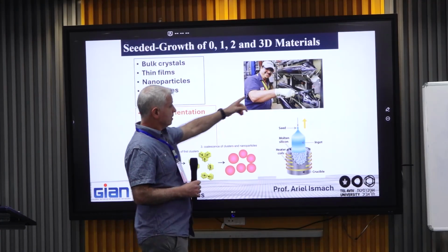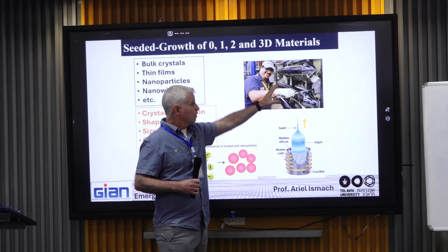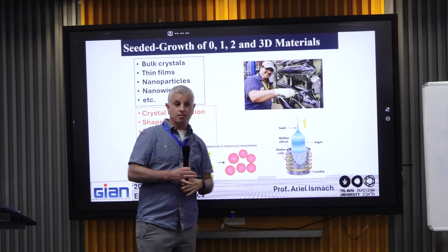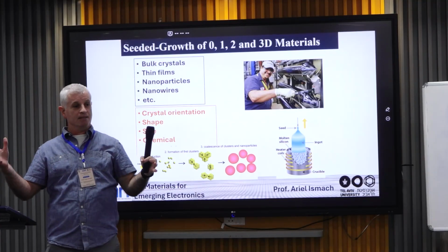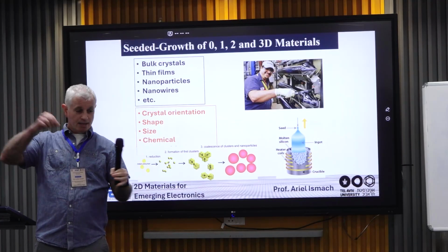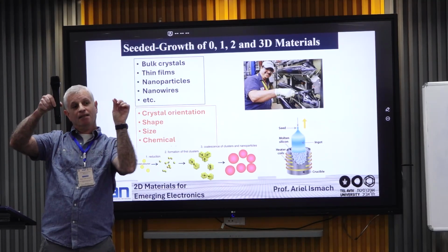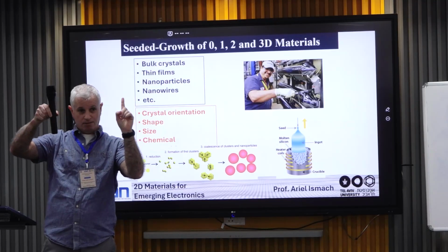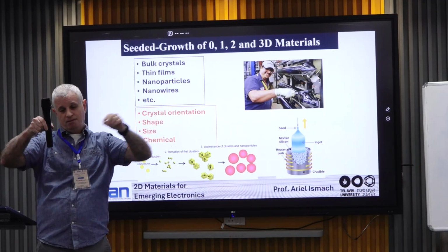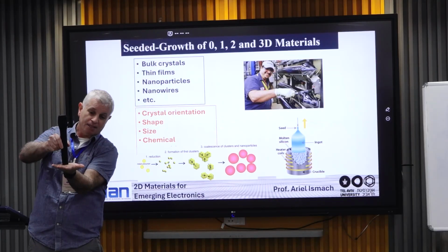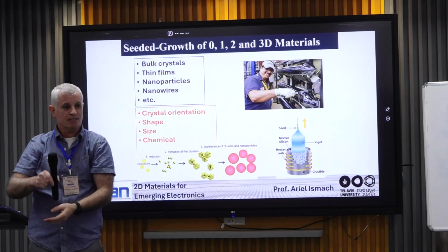I don't know if you're familiar with the Czochralski method, but all this starts from a huge crucible with melted silicon, for example. And then what you do is you come with a seed, a tiny crystal of silicon with the crystal orientation that you want to grow in these ingots, and you put it in touch with the bath, and then you pull it very slowly.